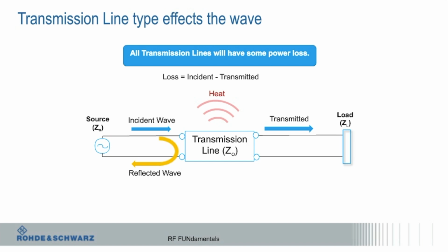People like to use lots of adapters and things, and you have to use what you have, depending on the instrument. But realize every time you put a connection in there, you're degrading the standing wave ratio of your device, so you're going to get more reflections. I've seen stuff where they have like 6 things all bunched together, and if you looked at that on a VNA, it looks horrible, right? And you can't just cal it out. People like to think that, but it doesn't work that way.